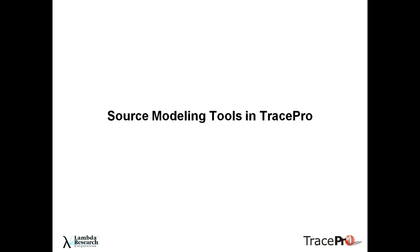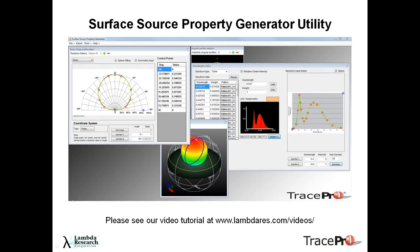So let's jump back here and take a look at a couple of the tools that we have available to help you set up your source models in TracePro. First is the surface source property generator utility. This utility lets us take a beam pattern and a spectrum right from a data sheet, whether it's an LED data sheet or any lighting manufacturer data sheet, and we cut and paste those graphs for the spectrum and for the beam pattern into this utility, and we just basically click on the curve to trace that curve. The more clicks we do, the closer we can follow the curve.